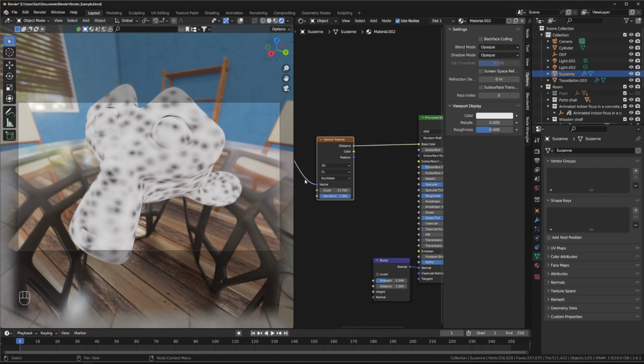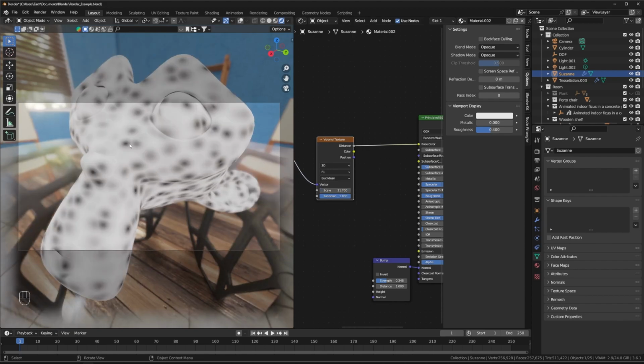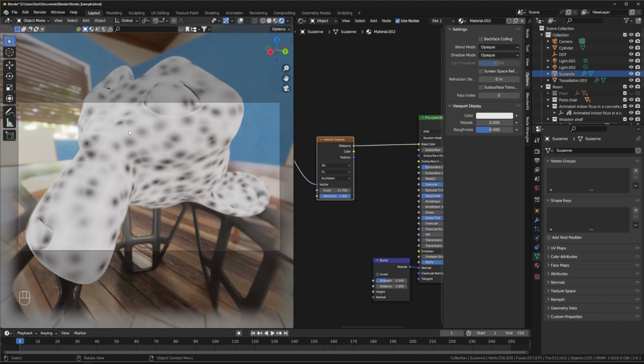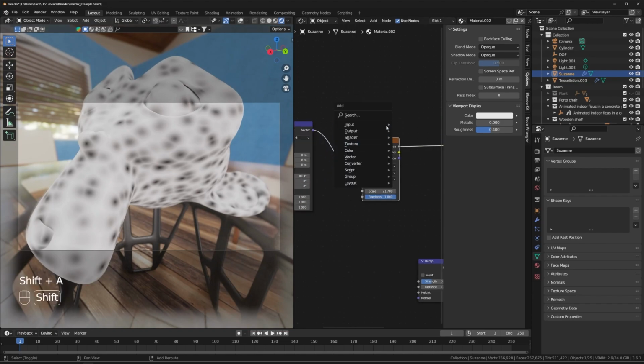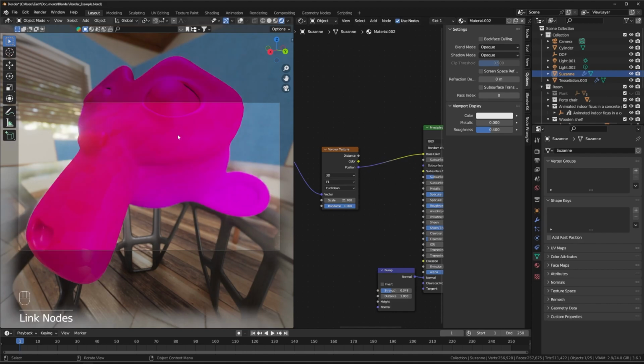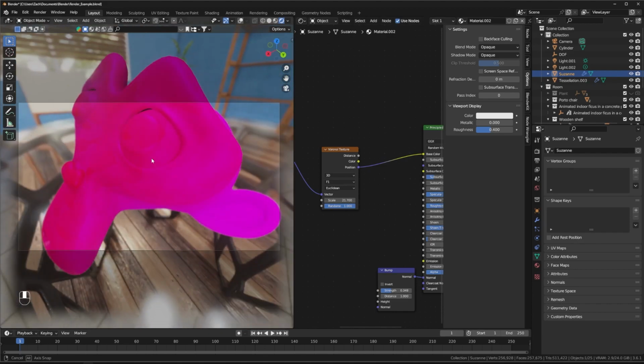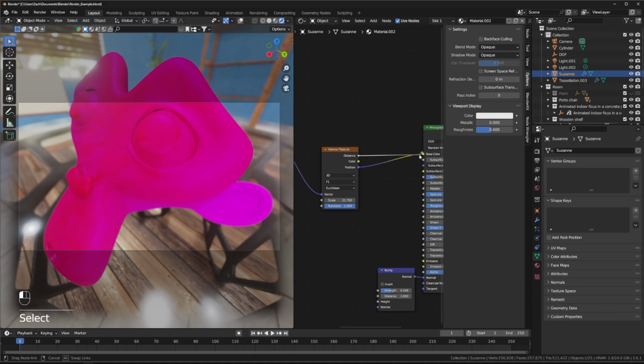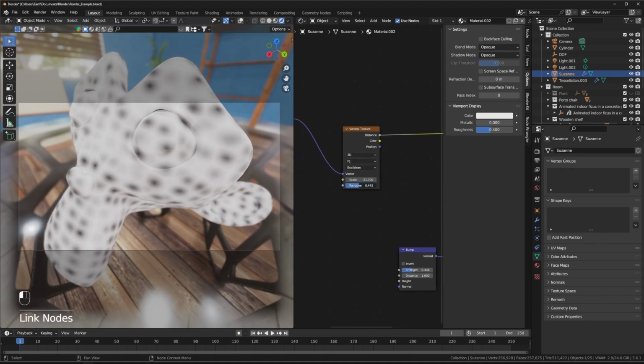where you have basically points distributed across the surface, and the closer you are to where one of the points is, the darker the color, and where two points are at equal distance from each other, you get a white color. So you end up getting this cellular look. You can also use position into color here, but you tend to not get great results from that. So distance or color is always interesting enough.